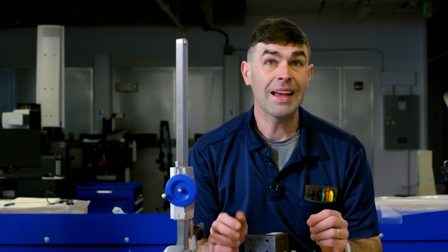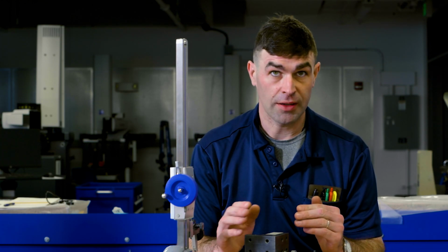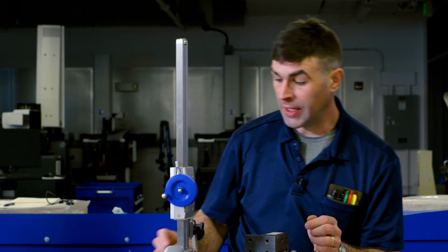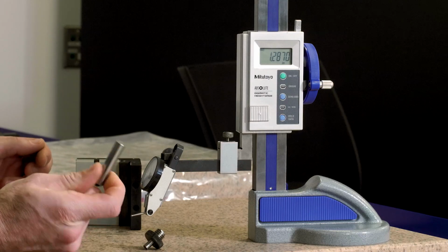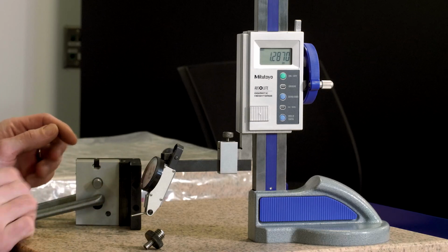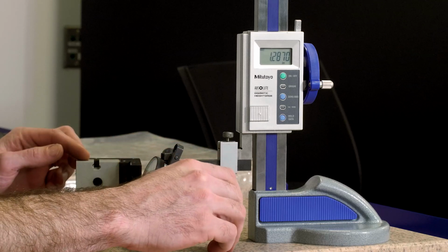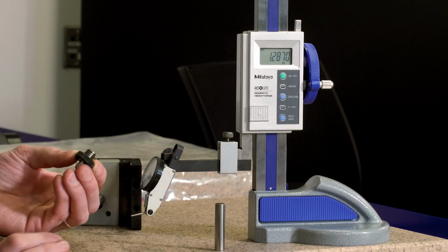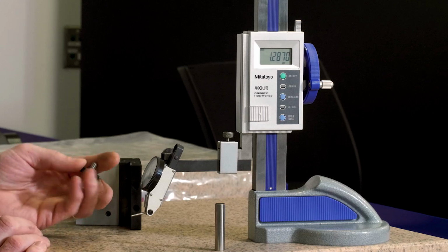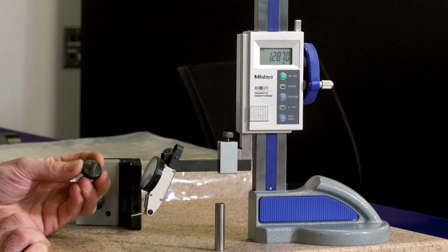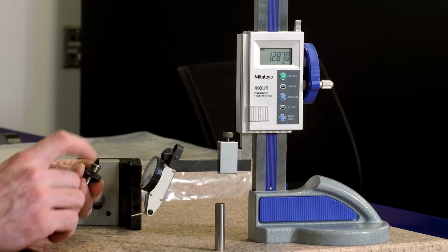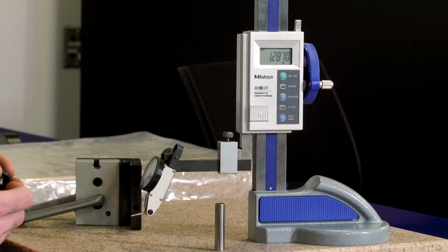In this part of the video, I'm going to show the difference between simulating our pitch cylinder versus our minor diameter. When we simulate our minor diameter, we can use a common gauge pin and treat it just like we would a hole. To simulate the pitch cylinder, we need a special gauge. This is used to locate threads, so this threads in, and it's got a pin so we can tell where the axis of the pitch cylinder is. Now it's not perfect. Ideally this would be the full length of the thread, but that's what I have on hand.